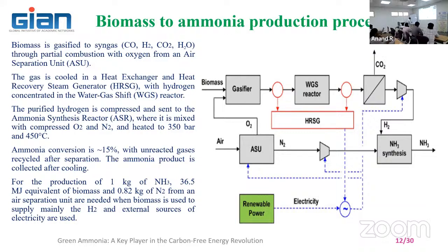We are producing the gas, that's why it's called producer gas. It's also called synthetic gas, syngas, the gas that comes out from the gasification. From the gasification system, there are 4 different zones: drying, pyrolysis, oxidation, reduction. The zone order may change for different designs. Ultimately, the gas comes out.